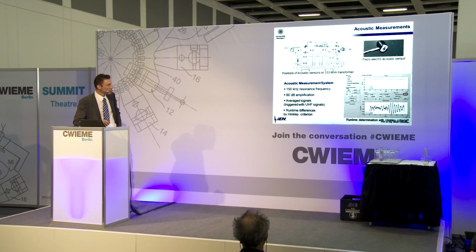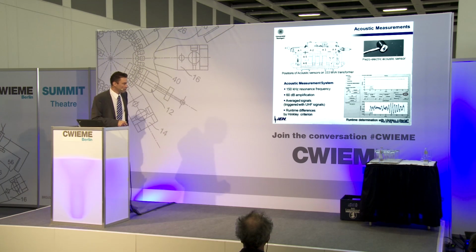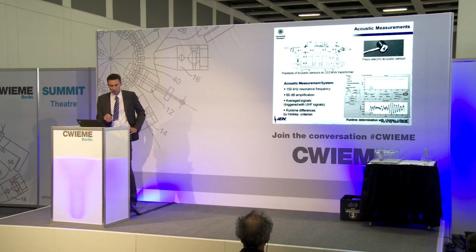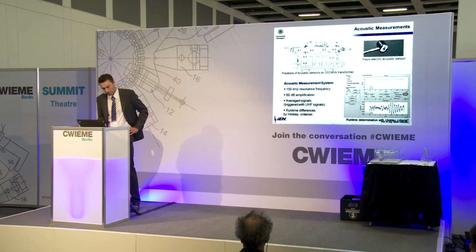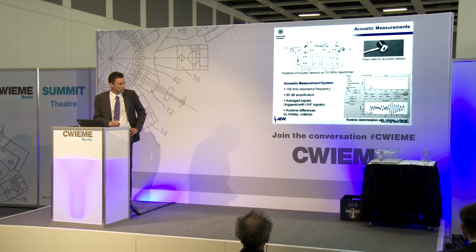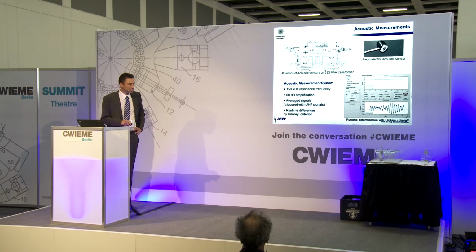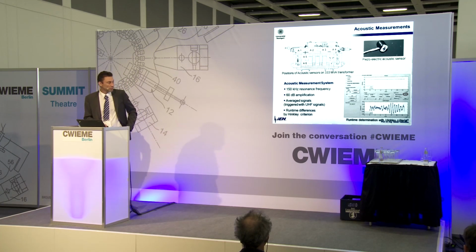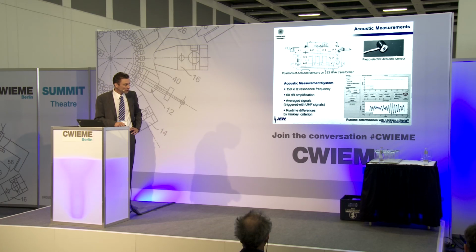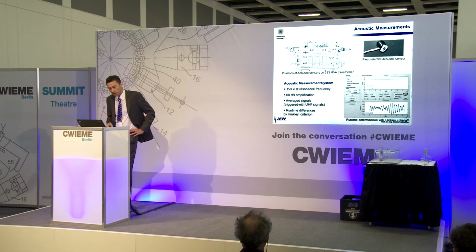So we additionally installed microphones here on the transformer tank, and then we measured the averaged signals. So we triggered on the UHF signal and averaged the acoustic signals. This was the result of such an averaged signal. It does not look as pretty as the signal before, so it's also not so easy, if you have this signal, to say, okay, this is exactly the arrival time, or is it here at the peak, whatever.